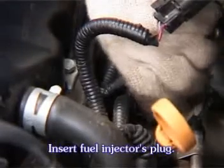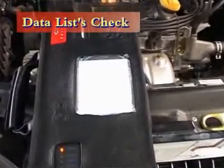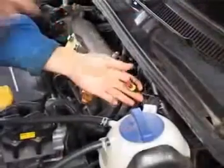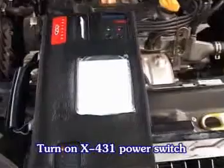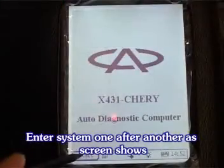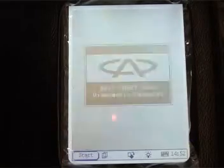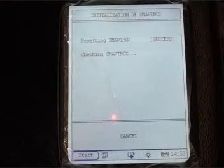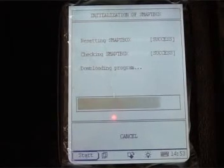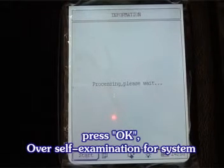Insert the fuel injector's plug. Connect the diagnostic plug. Turn on the X431 power switch. Enter the systems one after another as the screen shows. Press OK for system self-examination.